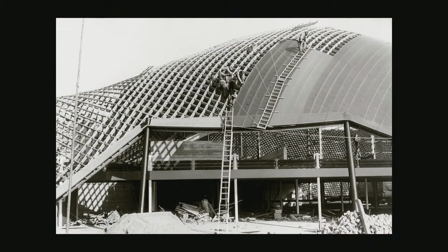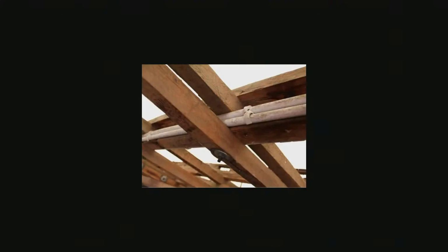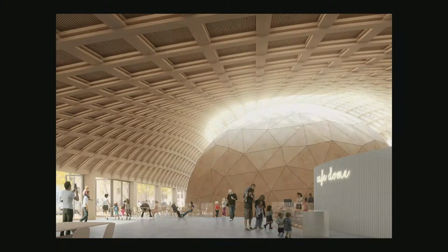And of course, you don't have much of those requirements that we have today for the buildings we are doing, but it's quite fantastic. This is the structure itself. 4 layers of 55 millimeters of battens just joined together with bolts and nuts. So the inspiration from Multihalle we kind of used in the Wisdom project, but instead we were using LVL laths in 4 layers, and then on top of that we had a thicker LVL shell, and everything bound together.